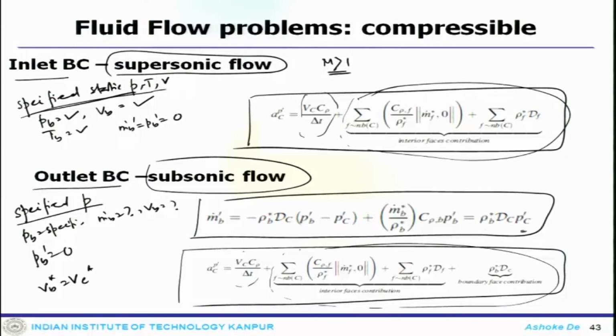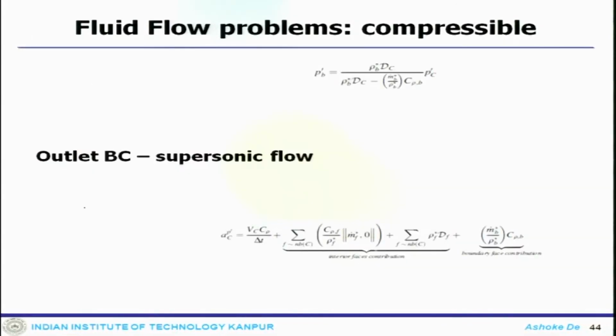And also one has to note that for the energy equation, a 0 gradient or del T by del N kind of 0 energy flux, or Neumann kind of boundary condition, needs to be specified, because this is a supersonic case, you cannot leave the energy equation unconnected. So, it has to be connected with the system.